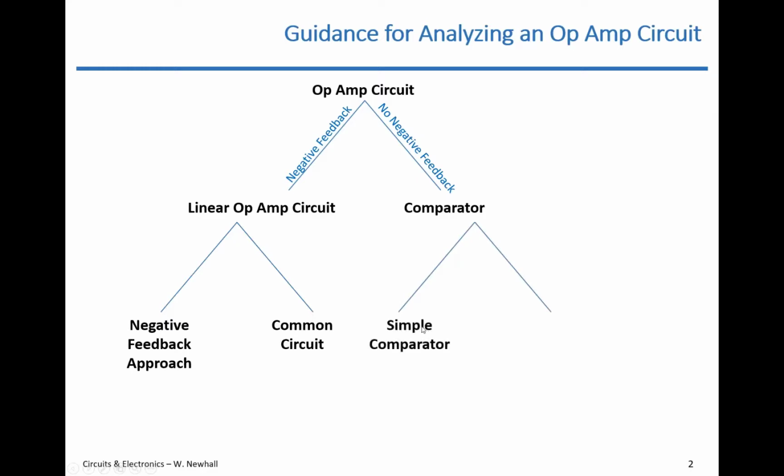The comparator is either a simple comparator, and by that I mean a comparator that compares two voltages, and if one voltage is higher than the other, you get a high voltage at the output. If the opposite is true, you get a low voltage. It's just like, I'll show you, a thermostat circuit.